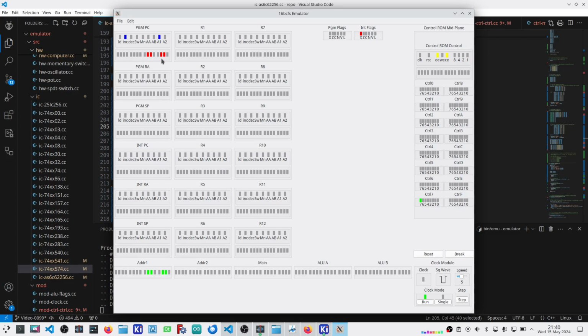Now I have this in quick copy mode. I want to redo this in pedantic mode and make sure that everything's good here. I no longer have the SRAM being overwritten, and that was a problem with how I was performing the reset. I was resetting the write enable last. It needs to be reset first. So that was a quick fix once I identified that.